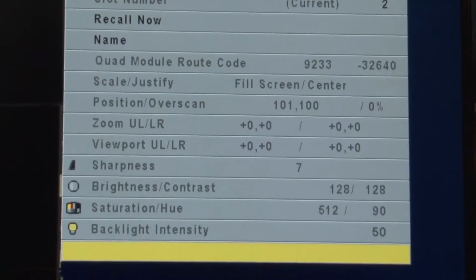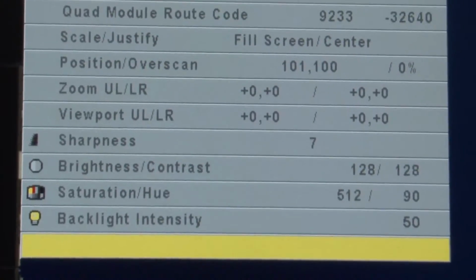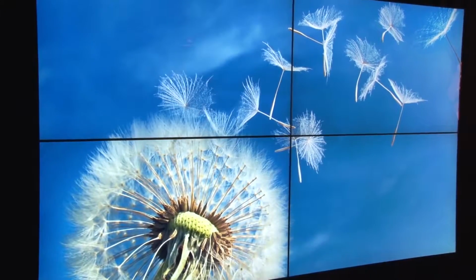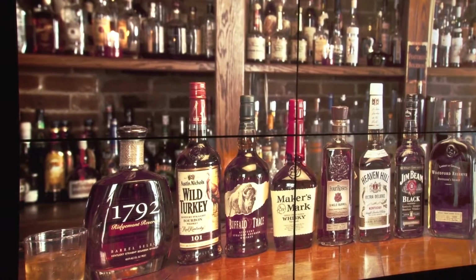The backlight intensity setting will affect the overall power load, so make sure that you have adequate headroom if adjusting the backlight intensity to near max brightness. Conversely, you can lower the power level by reducing the backlight.